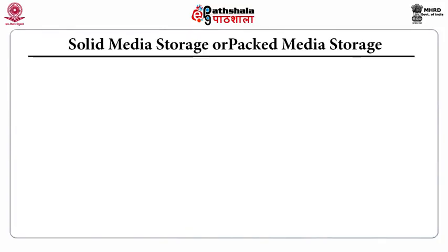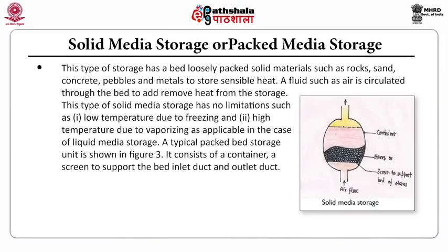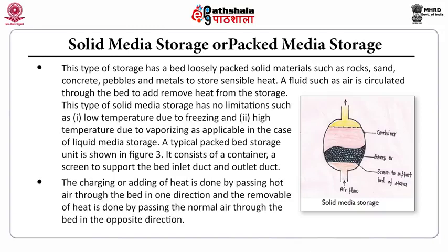Solid media storage or packed media storage. This type of storage has a bed of loosely packed solid materials such as rocks, sand, concrete, pebbles and metals to store sensible heat. A fluid such as air is circulated through the bed to remove the heat from the storage. This type of solid media storage has no limitation such as the low temperature due to freezing and high temperature due to vaporizing, as is applicable in the case of liquid media storage. So, it is better than the liquid media storage.